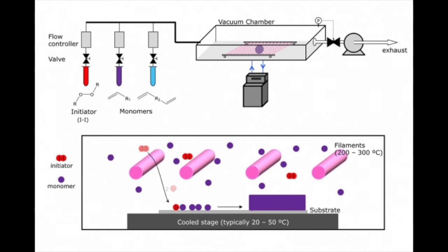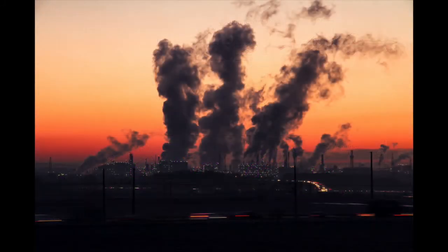The CVD technique described earlier is limited to the size of substrates that can fit inside reaction chambers, in addition to very high temperature requirements, 1000 Celsius, and long reaction time. Graphene oxide membranes formed by filtration method suffer from low filtration rates as water gets trapped between the layers of GO. Toxicity. One major concern with graphene, like any other nanomaterial, is its toxicity to the human body.